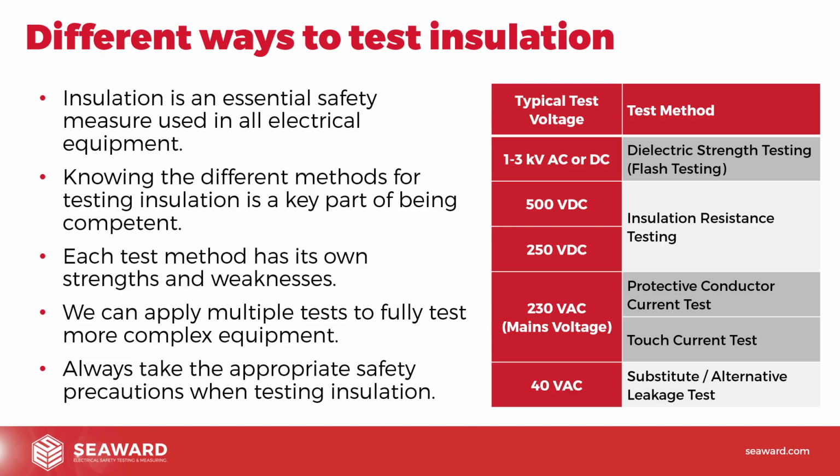Currently, the IET Code of Practice, the 4th edition that we're working to now, says don't do flash testing for in-service inspection and testing, because they've taken the judgment that realistically it's above and beyond what we need to do, and the risks of carrying it out correctly and safely outweigh the benefits we get from doing it. So the current guidance within the IET Code of Practice is we don't do flash testing, but there are companies who do, particularly, like I say, tool hire companies. It's still very, very common because they deem that it's necessary.